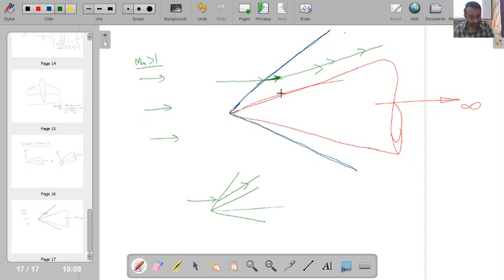So say if I take one assumption: because of this bend of the streamline, if pressure at different points on the surface of the aerofoil of this conical plane is different, then we will find that the analysis becomes very complex. So one assumption we introduce to the analysis is that over this surface, pressure and all the flow properties are constant. Okay, and ultimately what we find is that